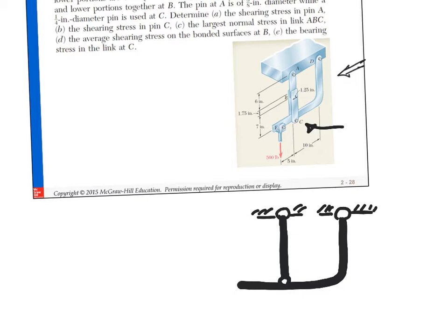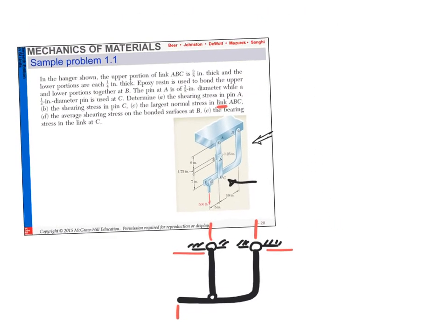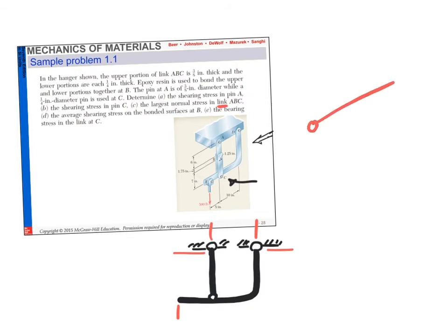Okay. Let's now consider that this is true. That means I have X and Y here, and I have X and Y here, in addition to my force here. Do you guys agree? Very simple. But there is an added value to the word link. The word link means it will not take any force, and I will zoom out to show this on a side, except in its axial direction. That means the force here is equal to 0. The force here is equal to 0.